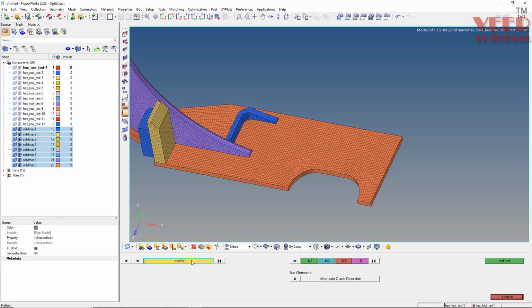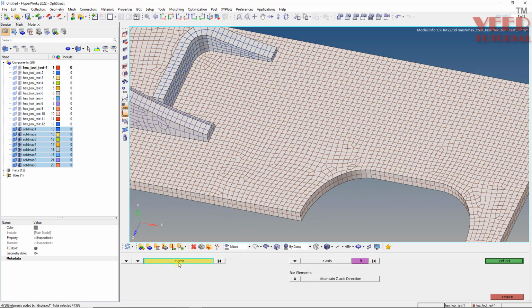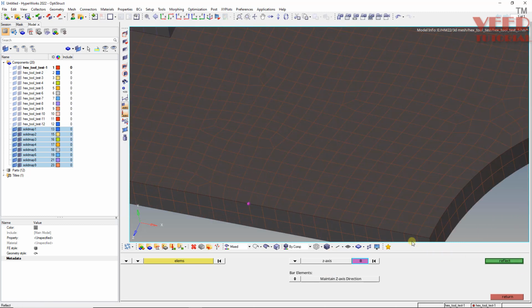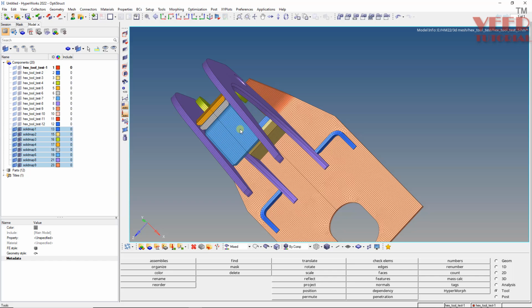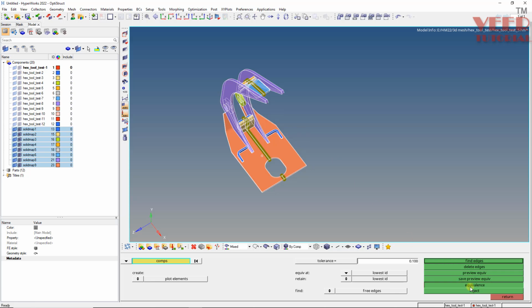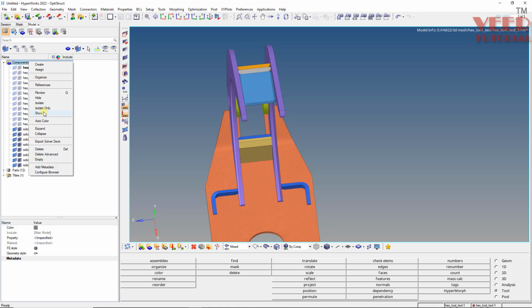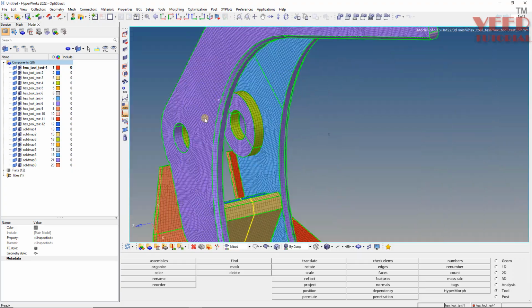Here select element, and axis we know is Z axis, and we can take any node, let's say here. Okay, element displayed, and duplicate in the original folder B. Let's say I pick this and reflect it. Okay, now you can see reflected. Then shift plus F3, select all, preview equivalence and equivalence. And now if I turn on everything, right click, show, you can see the mesh is completed.